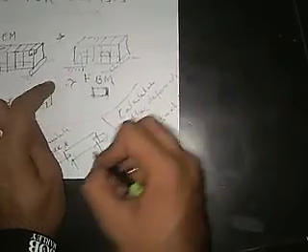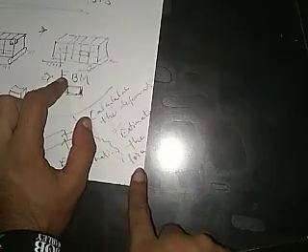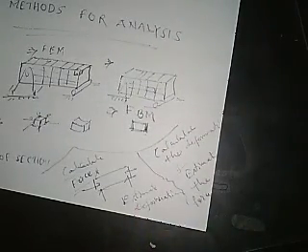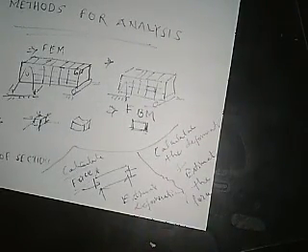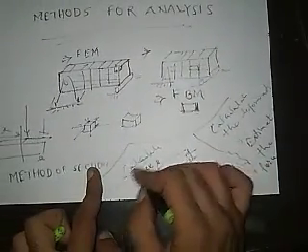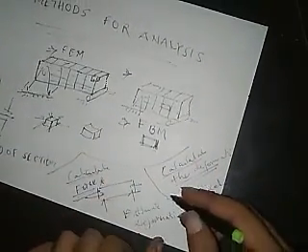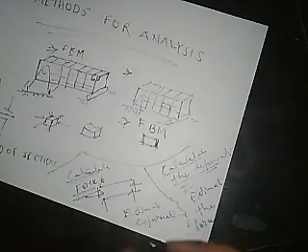Either you can follow a force to get the deformation, or calculate the deformation and get what will be the maximum load, or the desired or allowable load. So this method is called force method, and this method is called deformation method or displacement method.